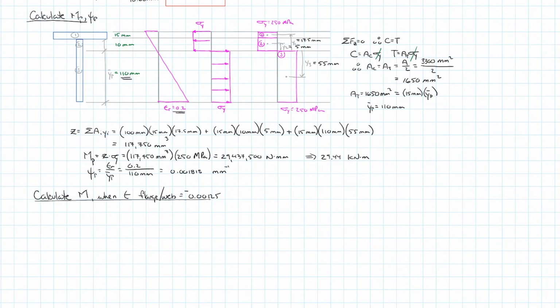If the elastic portion were to go into the flange itself, the asymmetry would be engaged and the neutral axis would start to vary between the elastic neutral axis and the plastic neutral axis, which would make the question somewhat complicated.